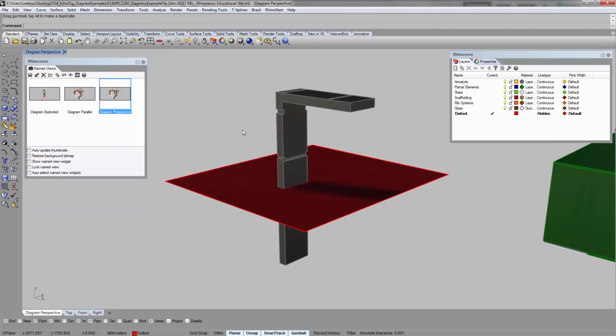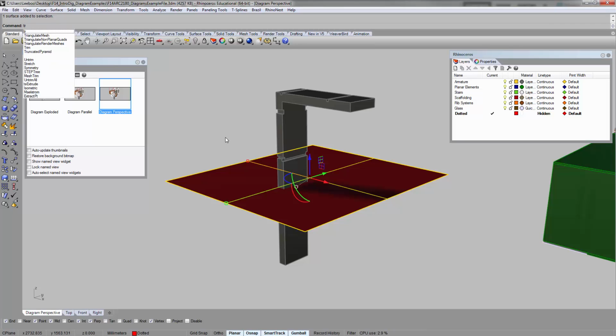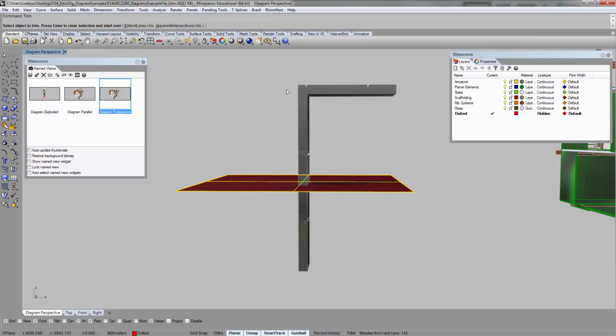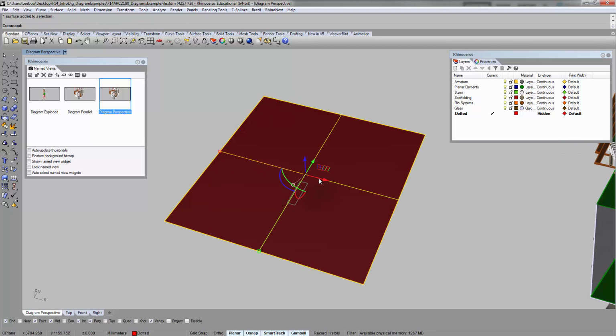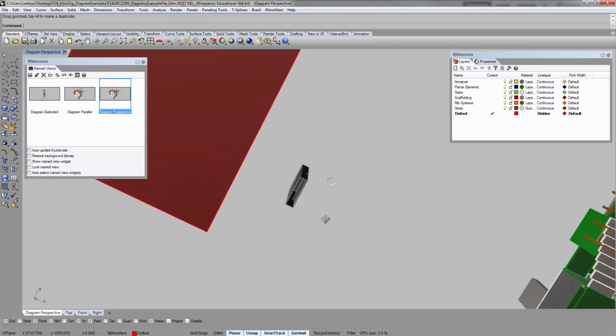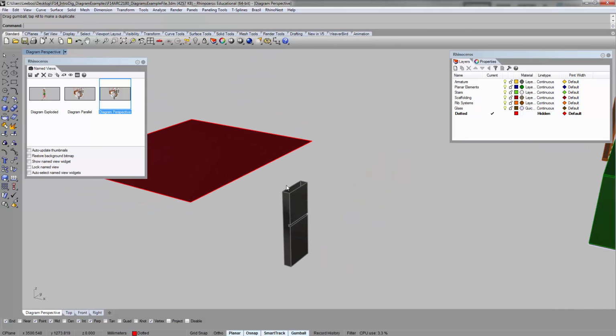But if you look at this, you can use this as the equivalent of the 2D trim tool. If you select the plane first and then say TR, trim, right, it'll ask you what object to trim, and you can say that, and basically it cuts it off, enter, right? And if you move this out of the way or delete it, basically, the object's chopped off.